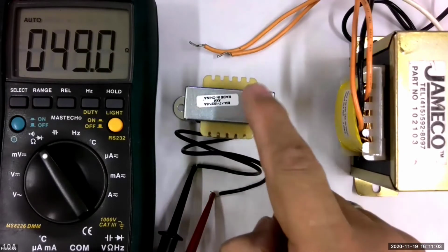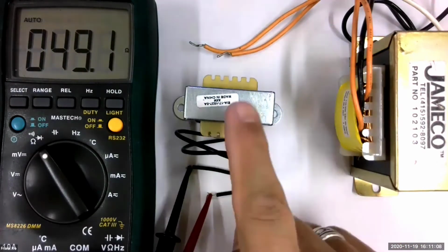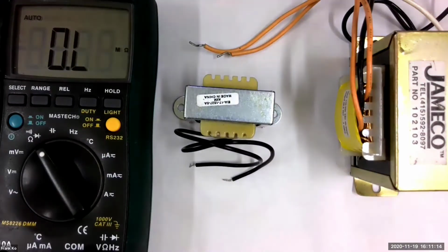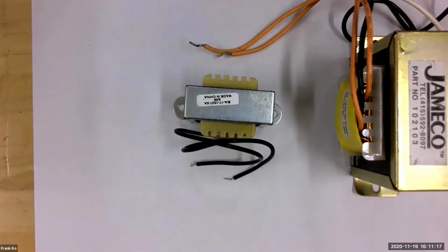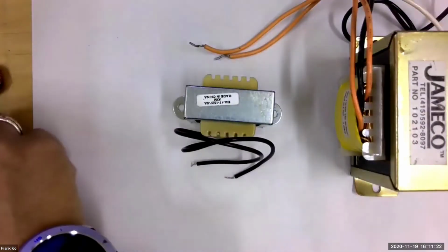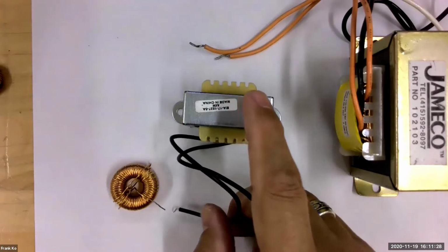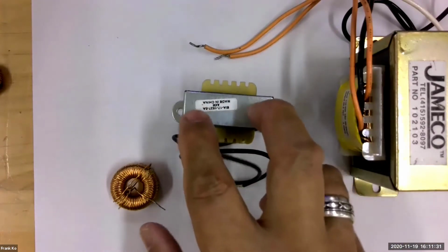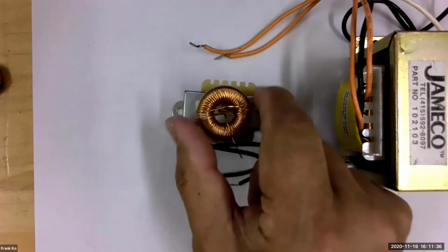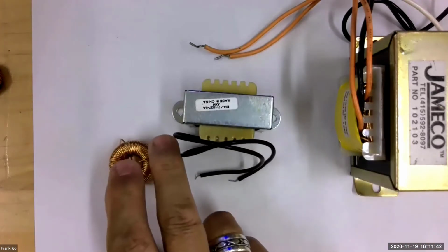So the characteristic we're concerned about is not the DC resistance of the component, but how it behaves when we run electricity through it. Now, there is a way of testing these inductors, and we will be testing them not with a digital multimeter for reading ohms. We can do that to see if there might be a break in the wire. Sometimes that does happen when you're working with an inductor. If the thing just does not behave the way it should, one of the reasons can be that one of the wires deep inside may have a fracture. And if there's a fracture, then this will not work properly.